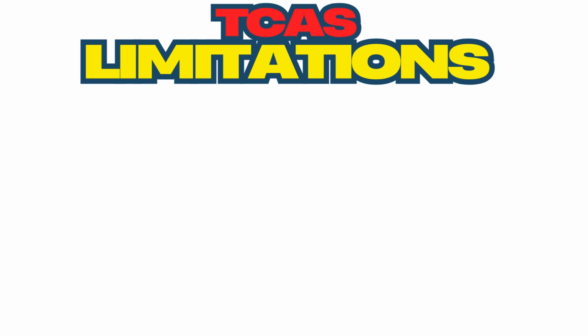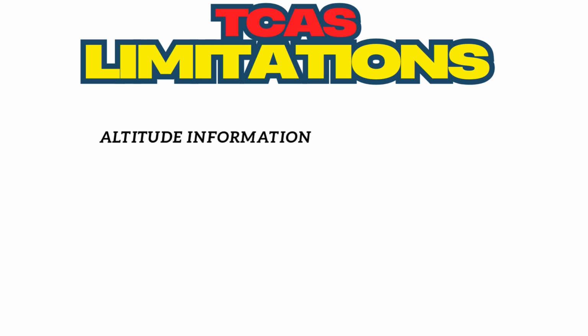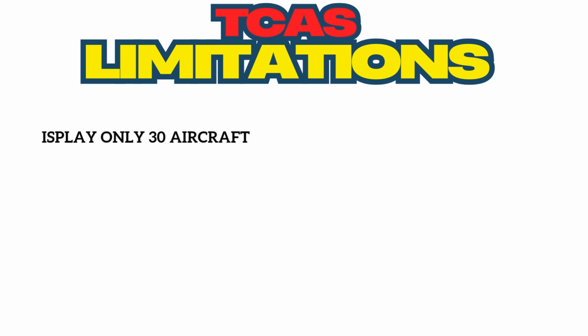What are the limitations of TCAS? TCAS, like any system, comes with quite a few limitations. TCAS relies on other aircraft being equipped with a transponder. These transponders should be working and capable of transmitting Mode Charlie altitude information. The maximum tracking range of TCAS is 14 nautical miles around the aircraft. Any traffic outside this range will simply not be displayed. TCAS can usually track a maximum of 60 aircraft at any given time, and display up to 30 of them.